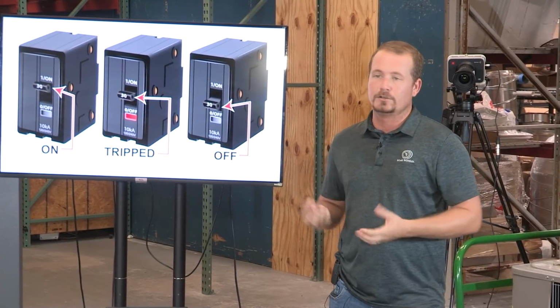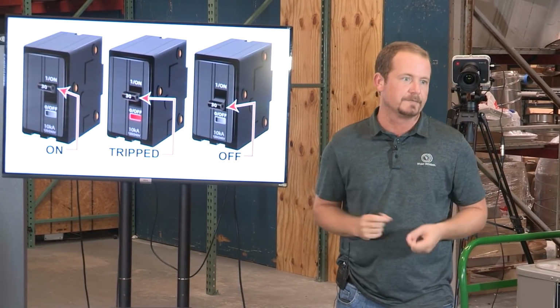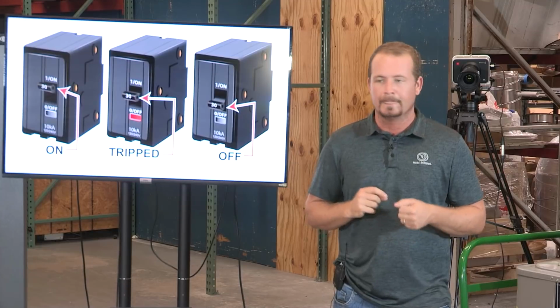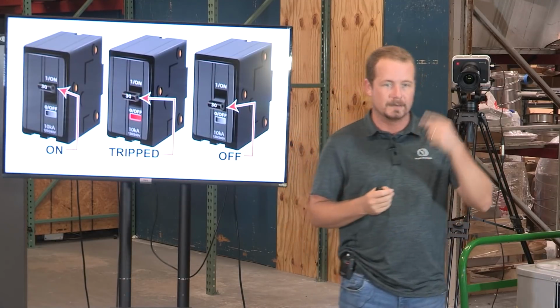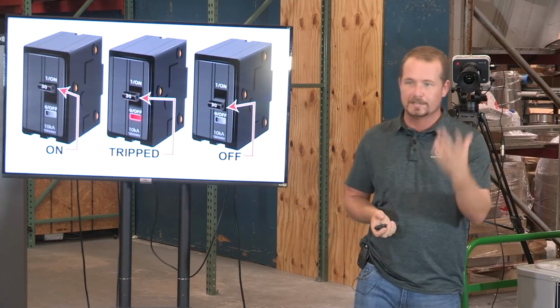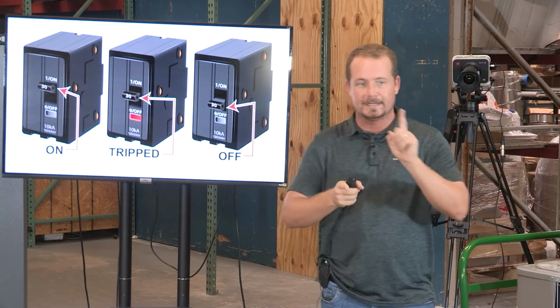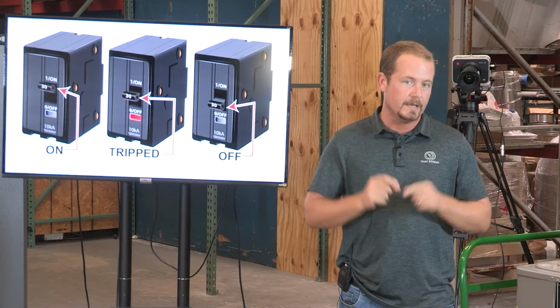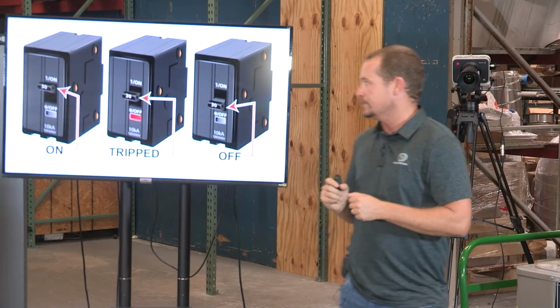If we're talking about a 240 volt appliance, it's the two legs of 240, 120 on each side, right? If it's a 120 volt appliance, it's going to be 120 volts to neutral. If it's a battery, it's going to be the two sides of the battery. If it's a transformer, on the secondary side, it's going to be your common and your hot on the other side. And so those electrons move in between those two sides.